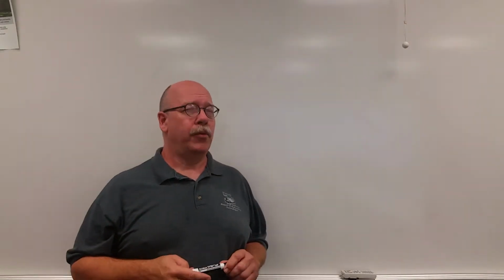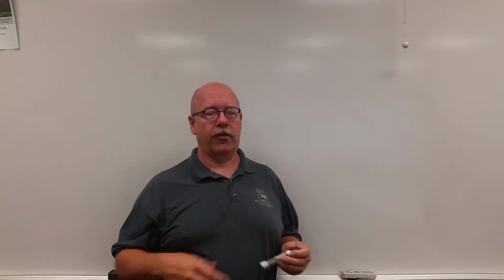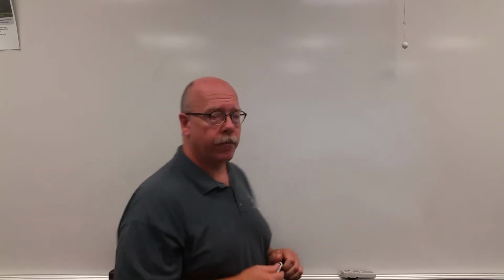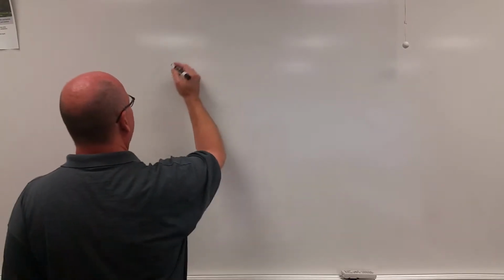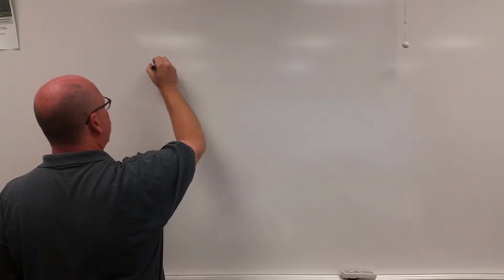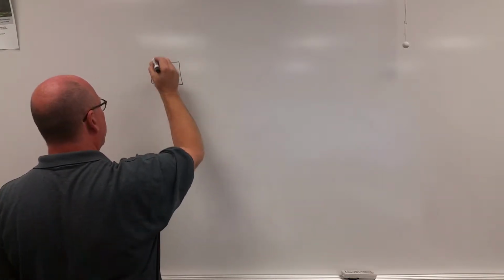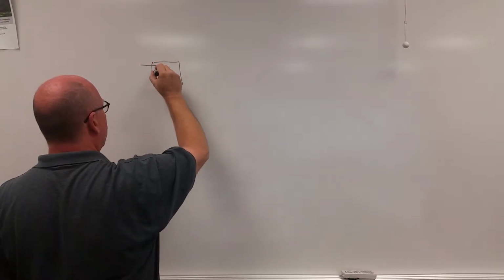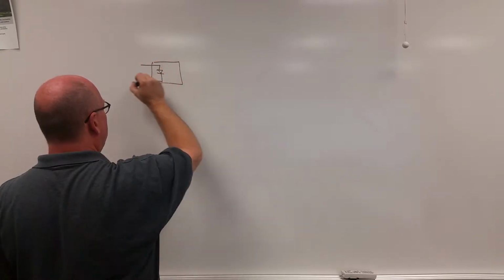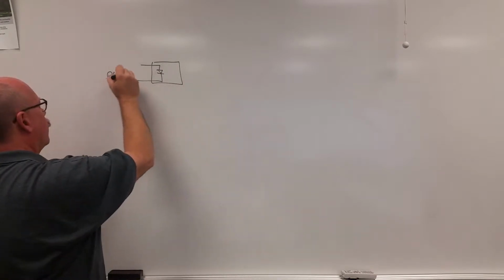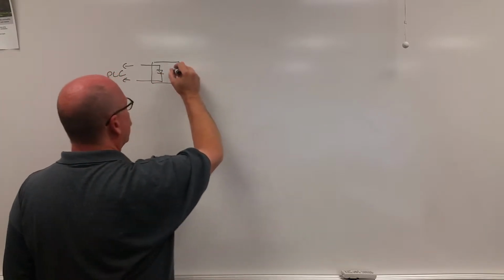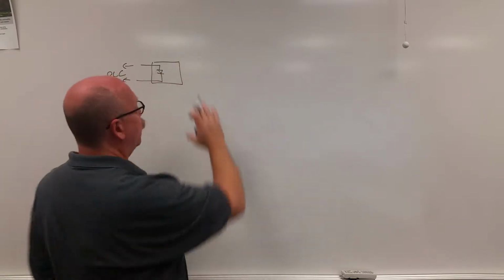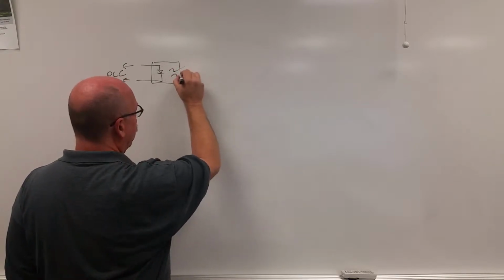Next, we'll talk about the output module in the Allen Bradley, specifically the 1769 OB16P. The P at the end of the module indicates that it's protected. So let's talk about what the output looks like. From the PLC itself, there sits an optocoupler with the LED. And on the output side, I will draw outside of the box. However, it is coupled with light to it.